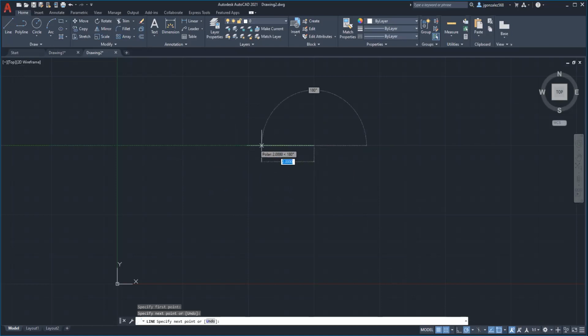Now, once you've made your 2 points to form a line, using the line command, just hit spacebar. It will end the command. Also, if you hit spacebar again, it will repeat the last command you did. So now it's back in line mode. So I'll make another line over here. And hit enter. So now those are 2 different commands that I can undo. If I type U and then enter, it removes the last command. And I can also click up here, redo or undo, bringing my line back. Okay, so nothing too complicated.